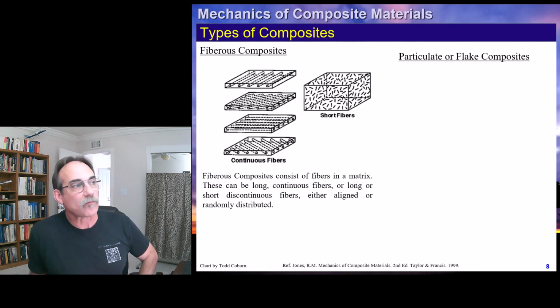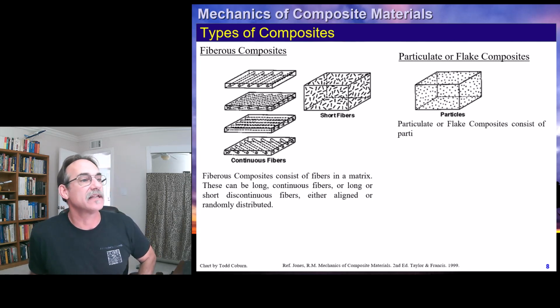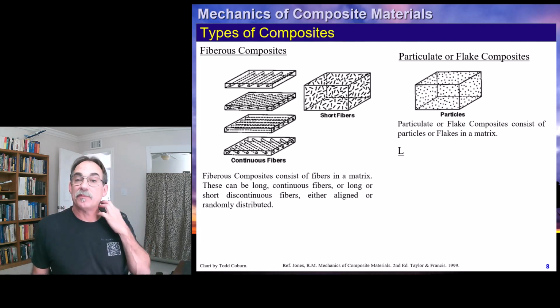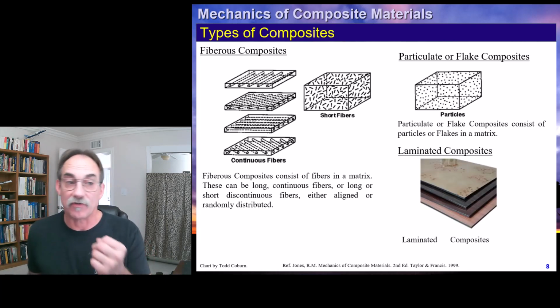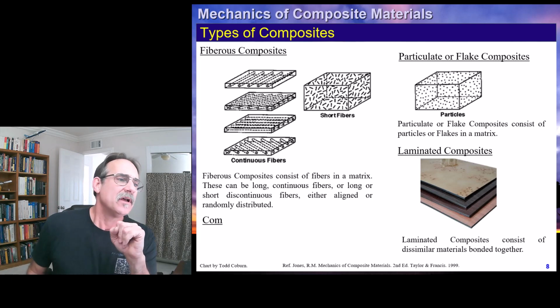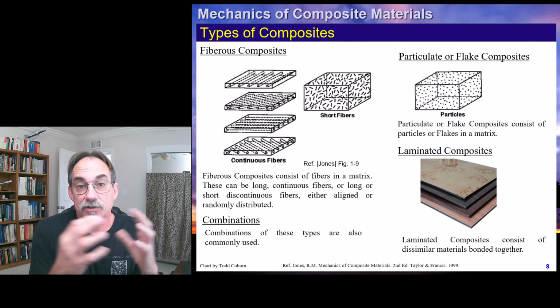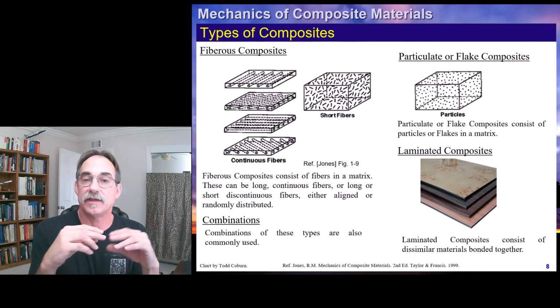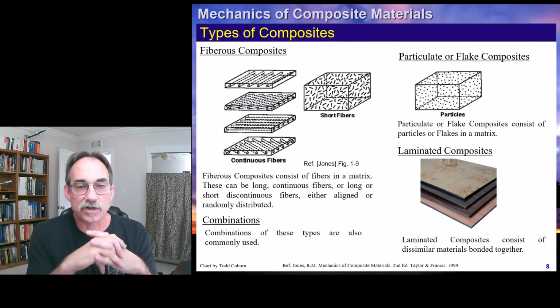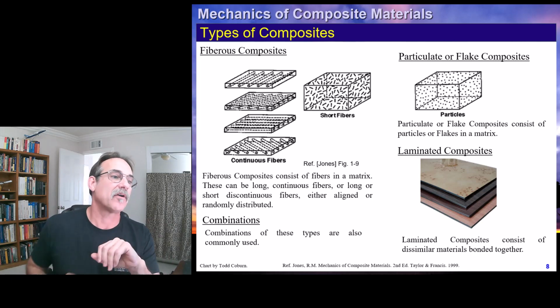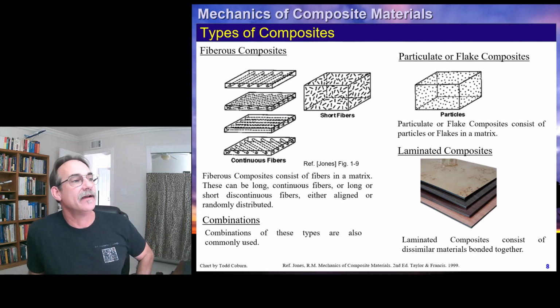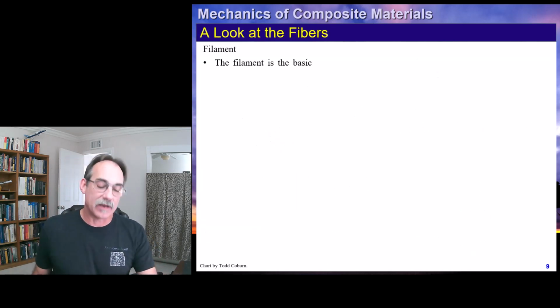We also use a wide range of other things like short fibers, particles. A lot of times the particles you may see are ceramics, especially for high temperature. And then a lot of laminated materials may be isotropic materials or pseudo-isotropic materials. You might have aluminums with a balsa wood core, or something like the old floor panels in a number of aircraft, and any combination of these. We're going to be dealing with sandwich kinds of structures also in this class a little later, once we get classical lamination theory under our belt.